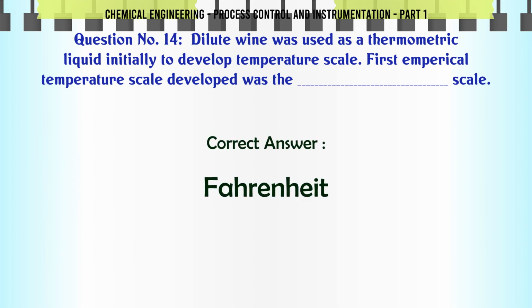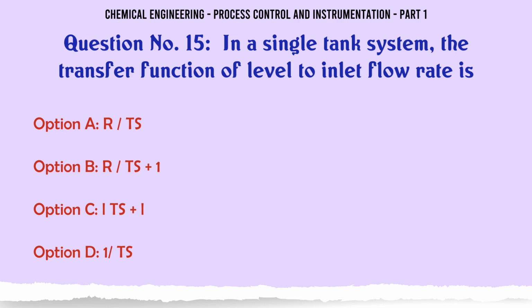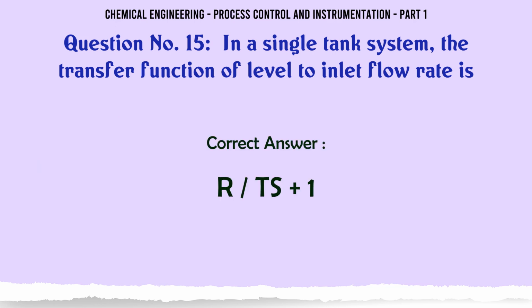In a single tank system, the transfer function of level to inlet flow rate is A. R/S, B. R/(TS plus 1), C. L/(TS plus L), D. 1/TS. The correct answer is R/(TS plus 1).